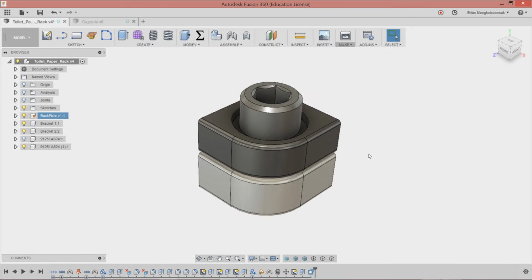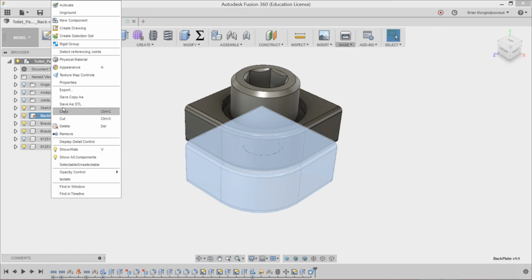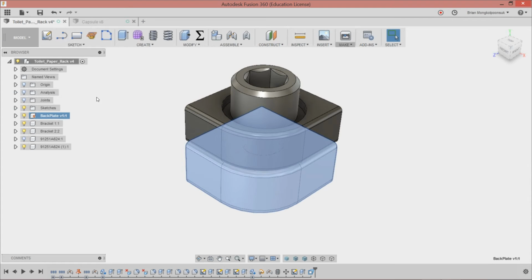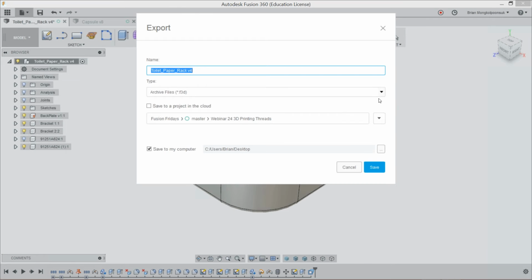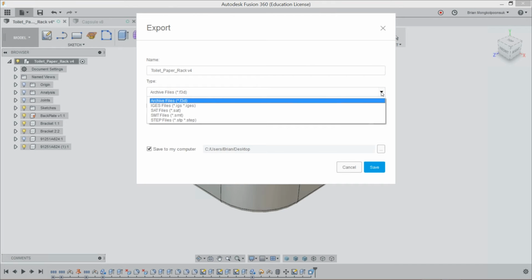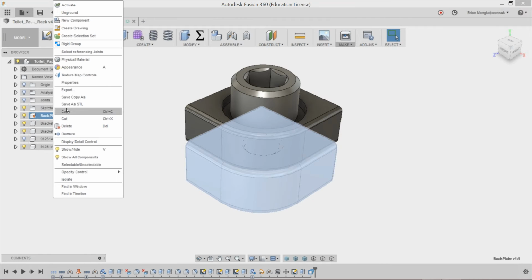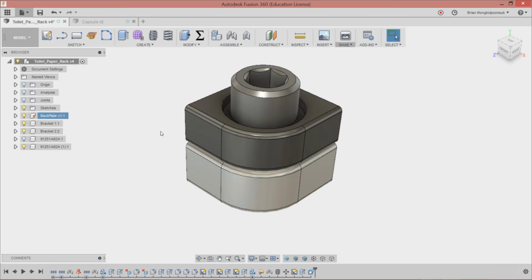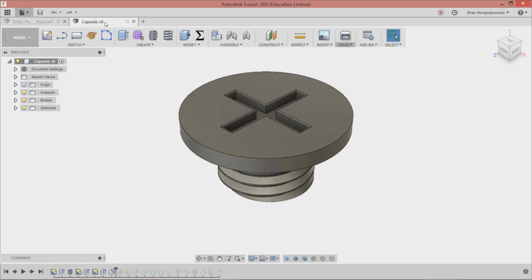All right. Also, people wonder why it is located here. People would ask me, oh, can you export as STL? Because they would normally go through the export tool here, and yeah, you wouldn't find the STL file type here, and that's why it's hidden in this component here. You would right-click and save as STL there. All right. So yeah, let's go to the next example here.